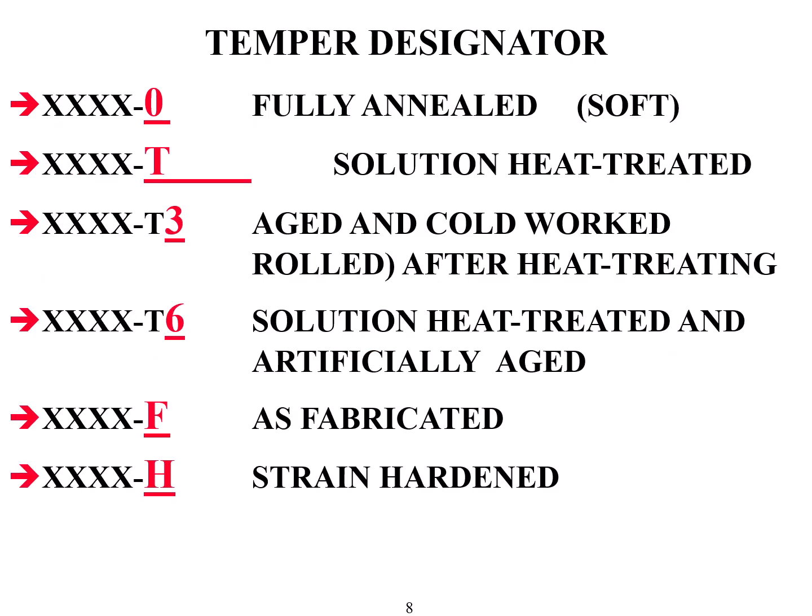The designator behind the 4-digit identifier will be our temper designation. Here's a list of common and very important temper designators for different metal, and there's some FAA questions dealing with it. Now, the very first one is O. That means the metal is fully soft. It's not been heat treated to harden it.